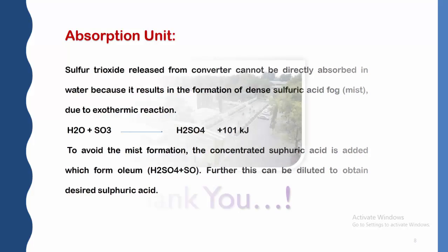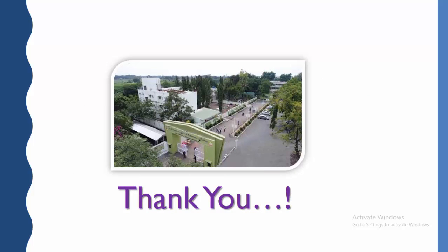So with this we can say the manufacture of sulfuric acid by the contact process is very simple. It has 5 different parts. First, the raw materials are taken in the burner or pyrites, heated at approximately 1000 to 1500 degrees Celsius, and further passed through the purifying unit, in which all the gases are purified and sent towards the converter, where the reaction takes place.